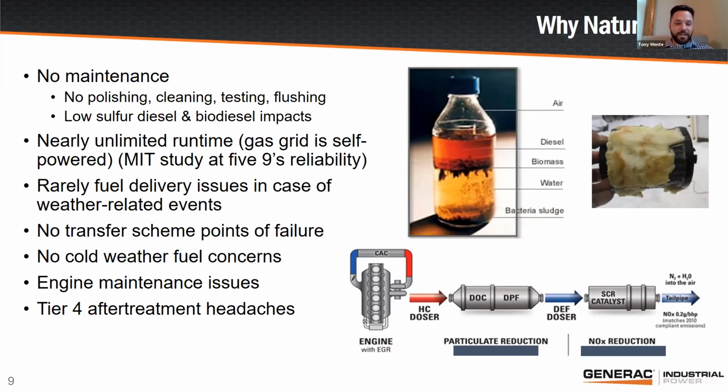I was just saying, if you want to use that diesel engine outside of emergency standby, so outside of a utility outage, you now need to have a Tier 4 final product. From the EPA, that's the requirement to have a very complex aftertreatment on top of your diesel to make sure it's extra clean out of the emission cleanup system.